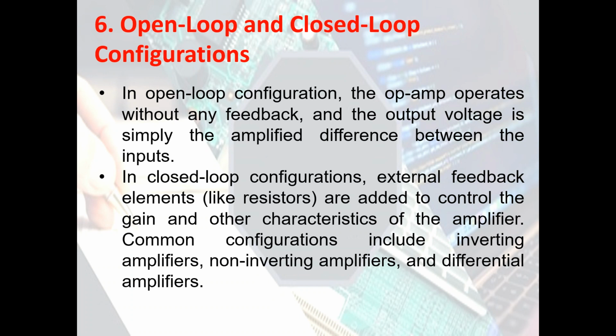In terms of the advantages of closed-loop configurations, number one, improved stability and reliability. Number two, reduced sensitivity to component variations. And number three, precise control over the gain and other characteristics. In summary, open-loop configurations provide high gain but lack stability and control, making them impractical for most applications. Closed-loop configurations, on the other hand, offer stability, precision, and control by incorporating negative feedback, making them suitable for a wide range of electronic applications.